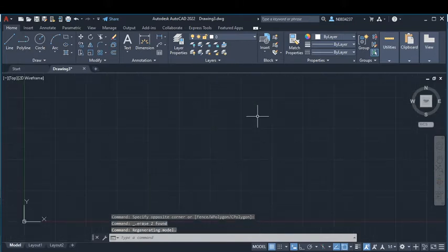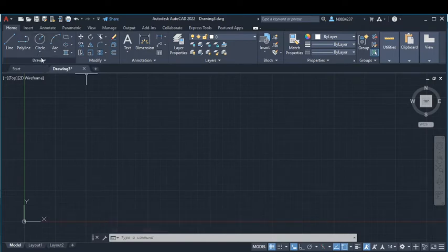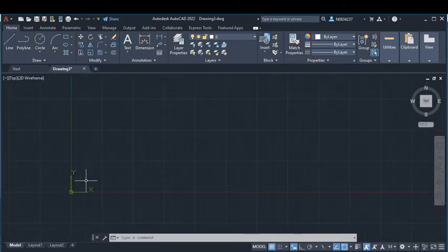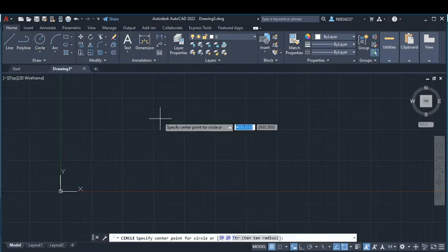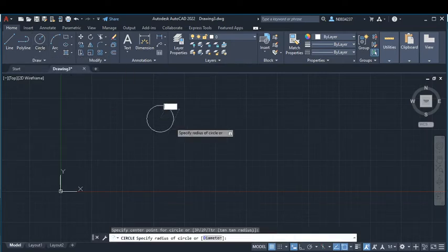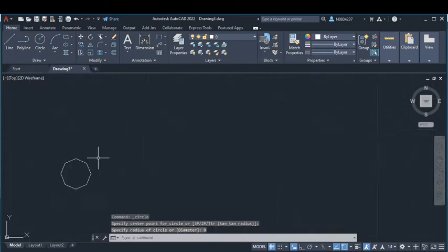We'll start by drawing some simple geometries and exploring the features. It doesn't matter where you draw it, the origin doesn't matter. You just draw it on the right side. Start with the center radius anywhere, and we'll do a 9mm. We'll have to zoom in for that.